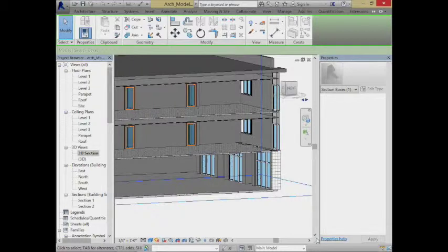So there is sort of a hierarchy. It plays out in design. It also tends to play out in the field. If there's a problem in the field, there's a hierarchy to who usually gets asked to move their stuff. Usually the plumbing and the electrician have to move things before the structural or the mechanical people have to move things. But trying to get all this work coordinated or even prefabricated before it gets out to the job site is really where the game is right now.